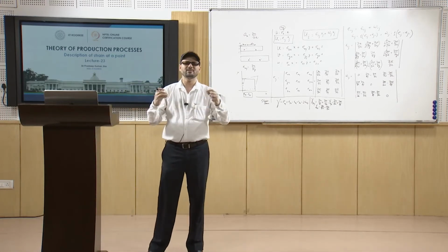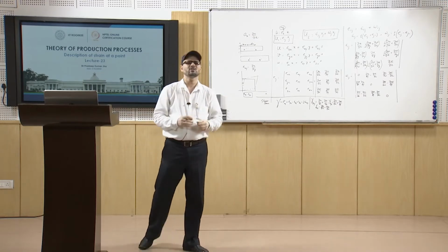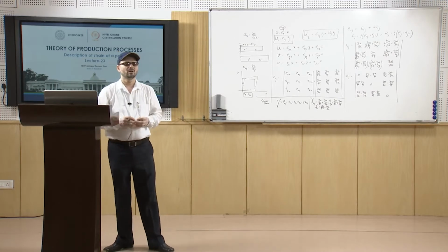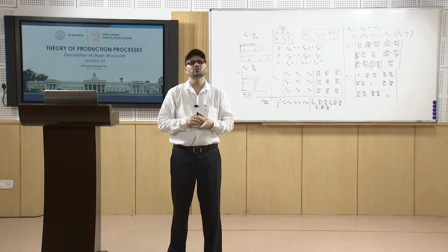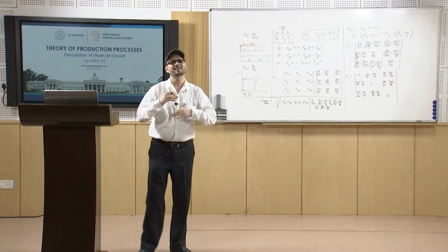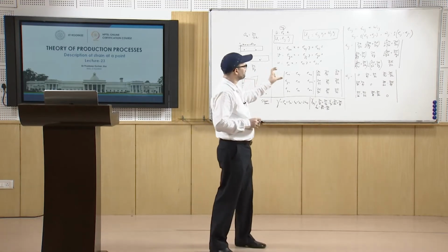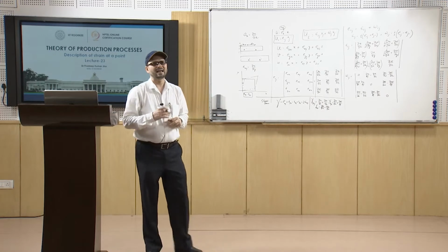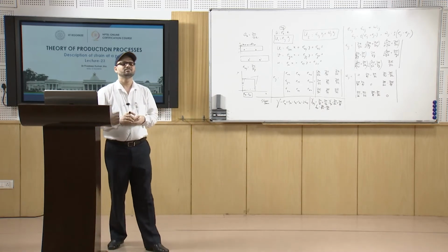That is because of the mean strain, or because of the tension or compression. And then you have the other component, that is the deformation. So one is change in volume and another is change in shape. One of the components is responsible for the change in volume, another is responsible for the change in shape.